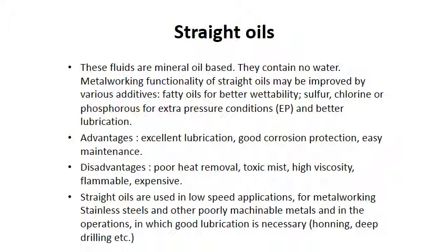Next we can study the straight oil. What is straight oil? These fluids are mineral oil based. They contain no water. The metalworking functionality of straight oil may be improved by various additives. Various additives means fatty oil for better wettability, and sulfur, chlorine and phosphorus for extreme pressure conditions and better lubrication.